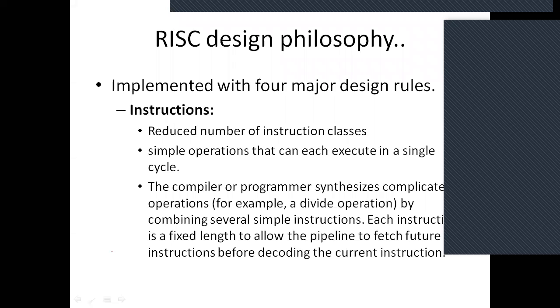As we know how a processor or controller works, any processor's basic operation is to read the instruction from memory, decode it, and execute it. This is the basic concept of any processor, from the basic processor to today's modern processor. If you take any processor, this is the basic operation that will be performed by any controller or processor when it is powered on.